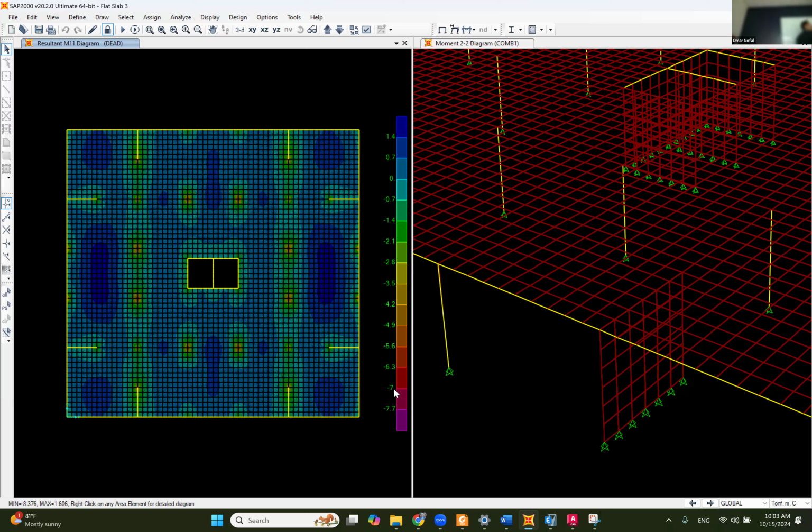That's a very, very stiff element. And then an earthquake hits and shakes the ground, or a wind load is distributed on this building this way, right? These columns are not going to absorb the earthquake load, because to resist the load, you need to have a deformation, right? But you have a big element here to resist. So this column is not going to have a deformation until this wall deforms. If this wall is stiff enough not to deform with this load, this column is not going to feel anything, okay? So this is the main resisting element. Maybe it takes 90% of the lateral force, and then the columns and the frames take 10%, okay?